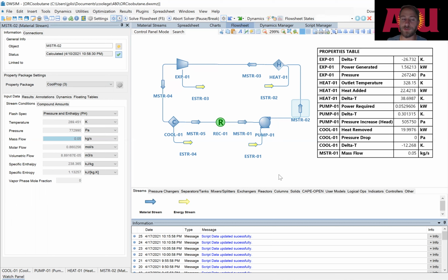And just while I have it really quick, when I say CoolProp, it's an open source database that's a lot like RefProp, and RefProp is just a national database for different thermodynamic properties of all kinds of working fluids. And that one you have to pay for. CoolProp is open source. It matches the RefProp data very, very nicely. And so it uses pretty much those steam tables. So we use CoolProp here, it works great. And then with the MATLAB function, which I'll introduce in a little bit, we also use the CoolProp package. That's all for this simulation.